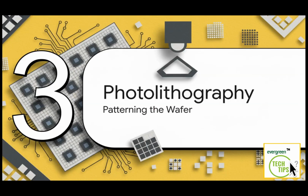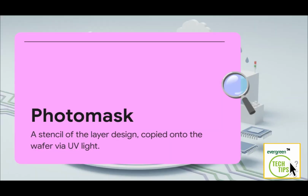Photolithography and patterning the wafer. This right here is the absolute critical path for patterning incredibly small interconnect layers simultaneously across the 230 individual CPU chips sitting on a single wafer. The secret sauce for this mass replication is the photomask. Think of it as a 6x6-inch master stencil holding the exact design of the layer you want to pattern. Because they have to be so ridiculously precise, they cost about $300,000 each.